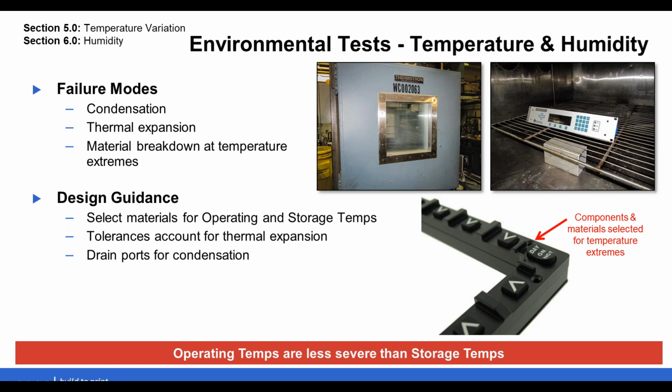If it turns out that condensation is an issue, that becomes less of a temperature concern and more of a waterproofness or water pooling concern. Drain ports, vents, grooves, etc., they all can be incorporated in the design to help mitigate any pooling from condensation.